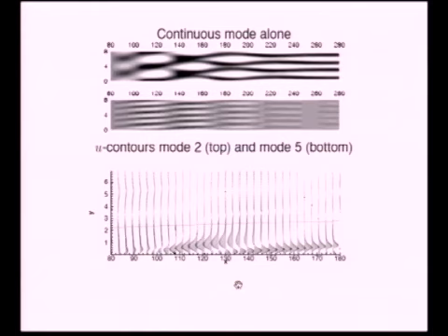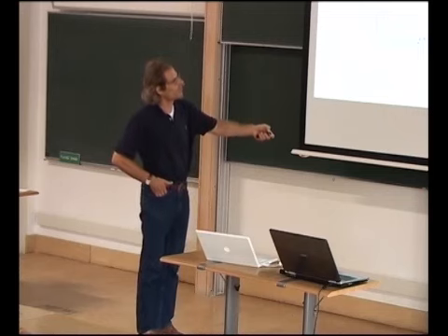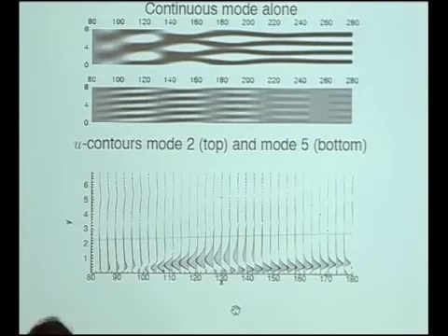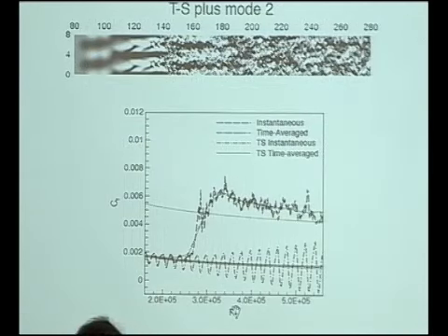So it's completely innocuous. It produces a disturbance, these jets, streaks, whatever you want to call them, but they don't transition. It's just an innocuous disturbance. And like I said, the skin friction wouldn't show anything. Here's a vertical section showing these jets. The negative jets are upward displacement, so they're moving upward, and the positive jets downward displacement, and they're closer to the surface.